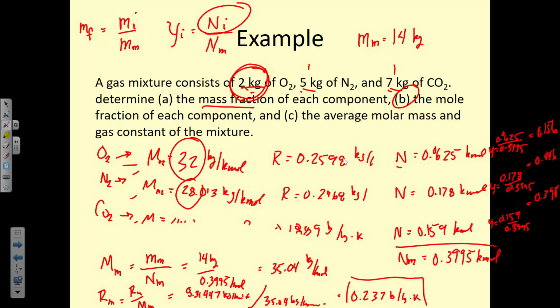And this is another point where you would do a reality check that this number should be on the order of between 0.1 and 0.8 usually. So looking at your gases, you see the R values for these, 0.25, 0.29, 0.18, so 0.237 seems reasonable. If you start getting really wacky numbers like 1.5, you need to go back and see what you've done wrong.